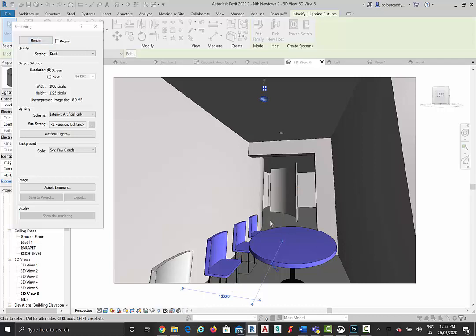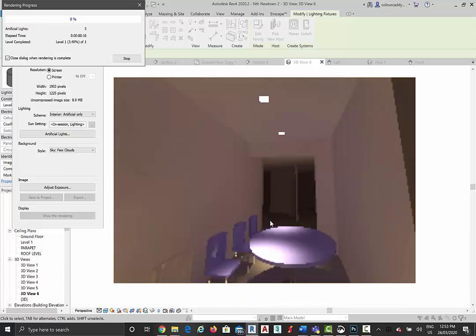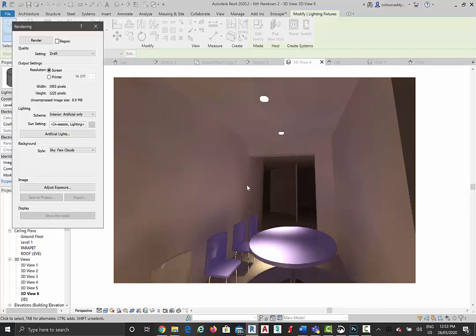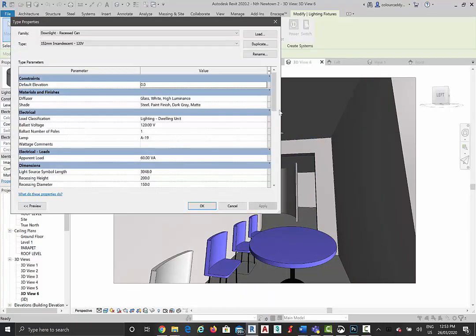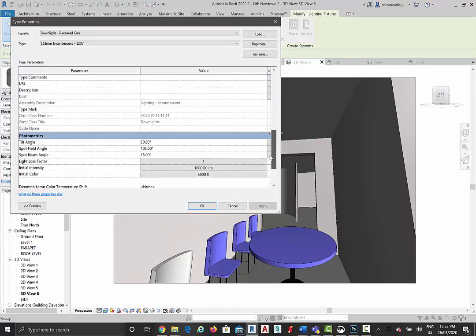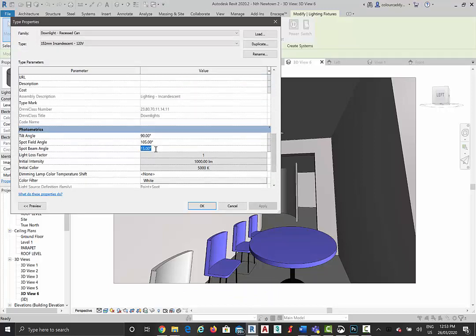In most spaces, you cannot see the edge of the light all that clearly. I know this one, having said that, it's because the bright spot is there. That's what we're seeing. We're not seeing the edge of the light. We're just seeing the bright spot. Okay, so a bit of trial and error. You also got to watch out with Revit. It's not the most physically correct lighting engine. So with 3ds Max, you get a bit more obvious control.